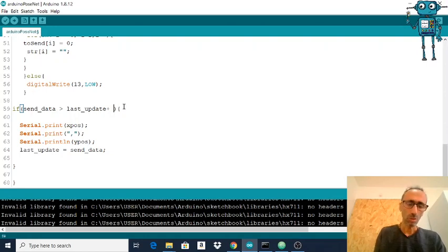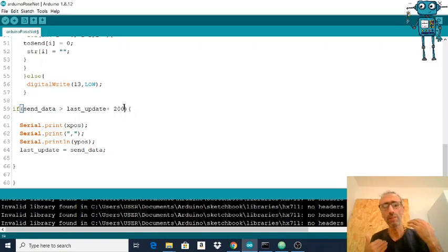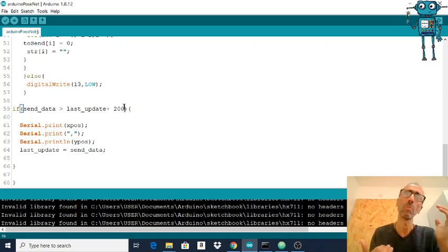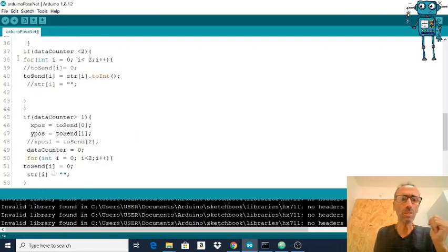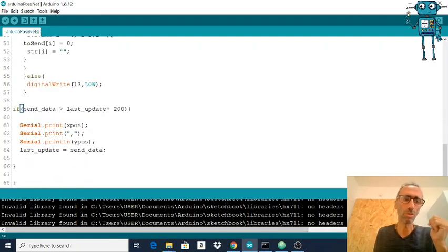But what this is doing is the delay is stopping the program. And when you say delay, all the program is stopped. Here we are sending the data every 200 milliseconds, but the rest of the program is continuing to work. So this is really, really important.